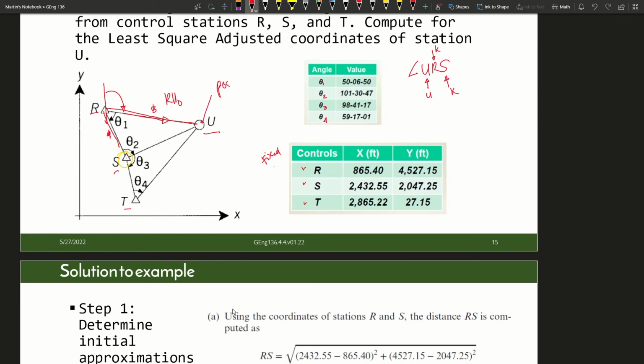So what's the purpose of determining this position in the early stage of this solution? This helps the adjustment to have at least a small amount of corrections because you already approximate the value based on your observations. But if your other observations are erroneous, it will lead your approximate value to be adjusted abnormally, which leads to a wrong answer.